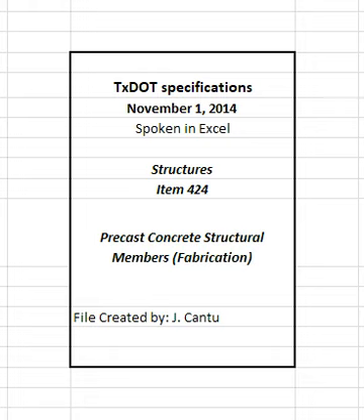Product with concrete that fails to meet minimum design compressive strength requirements will be reviewed. Concrete that has been determined to be structurally adequate may be accepted at an adjusted price based on the formula in Article 421.6, Measurement and Payment. If the engineer requires cores be taken to determine the strength of the in-situ concrete, the coring will be at the contractor's expense and in accordance with TEC 424A.